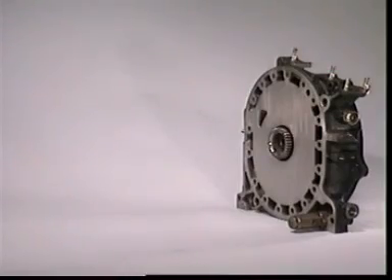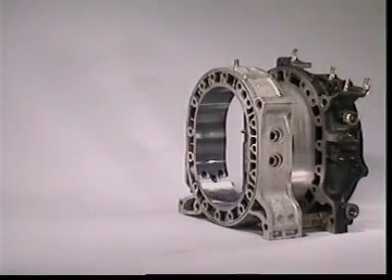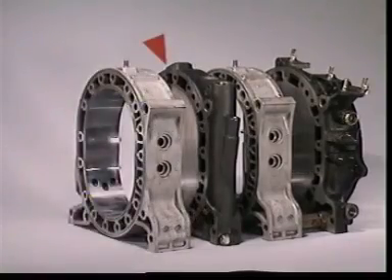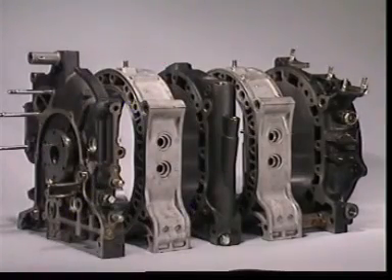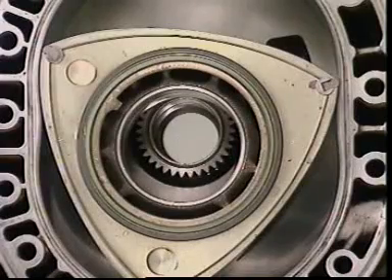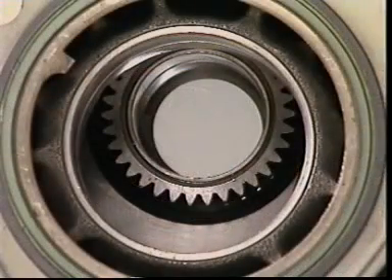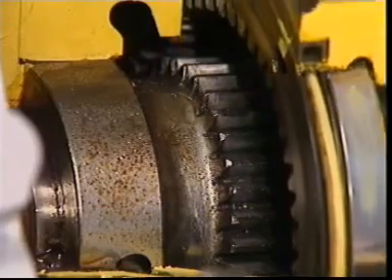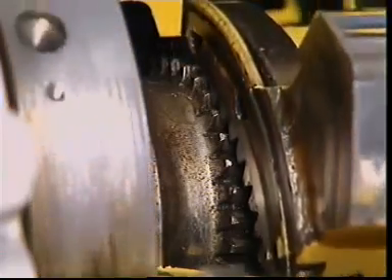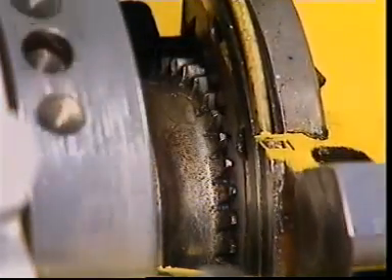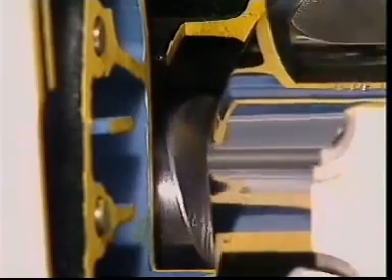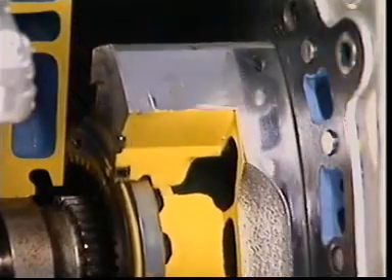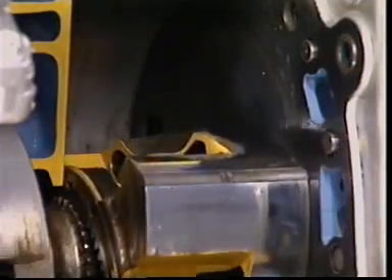Front and rear housings, or side housings, are bolted to each side of the rotor housing. If it's a 2-rotor engine, there is an intermediate housing between the 2 rotors. An internal gear in each rotor meshes with a corresponding stationary gear in the front housing and rear housings. When combustion occurs, the meshing of the teeth forces the rotor to walk around the stationary gear. This combines with the eccentric shaft to make the rotor follow the curved surface of the housing, and it gives the rotor planetary motion.